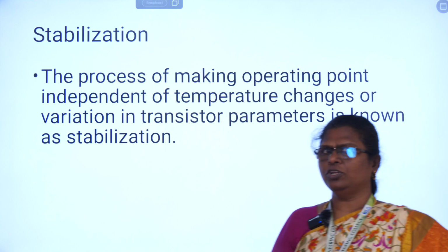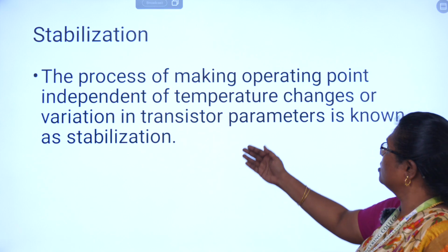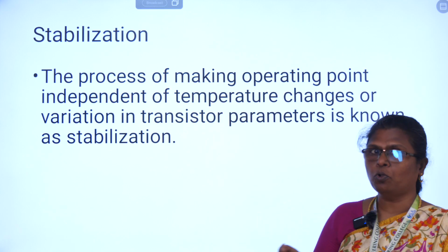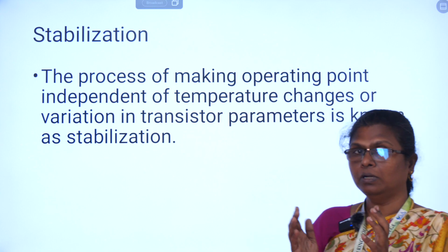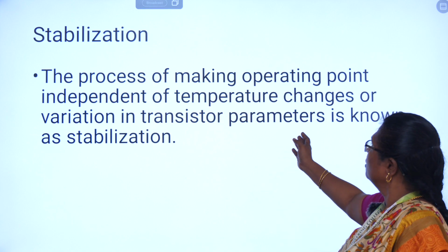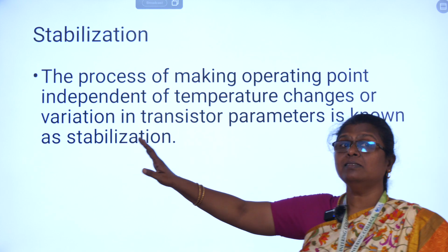So, what is stabilization? All these definitions are interlinked. Stabilization is the process of making the operating point independent of temperature. This process of making the circuit remain stable irrespective of the changes in temperature or transistor parameters, we call as the transistor being stabilized.